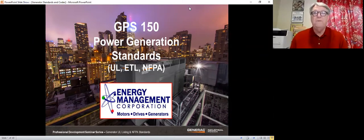Now, if you buy from Generac, from Cummins, from Kohler, from CAT, a light duty generator, let's say a residential generator or a commercial quality generator, those generators cannot be used as emergency generators or as legally required generators. And it's a real heartbreak because if you go to an electrical distributor and buy a generator, they don't have access to the emergency or the legally required generator product line.